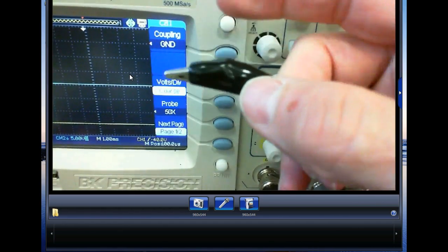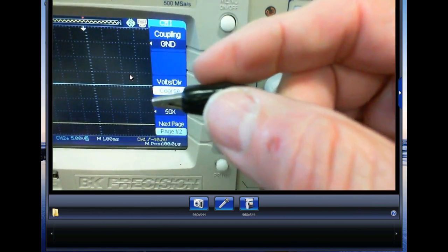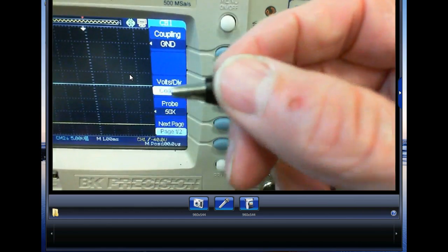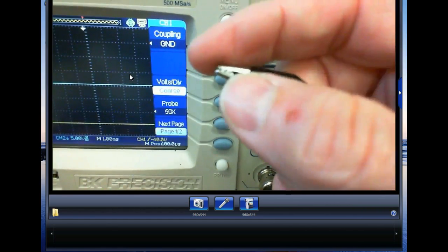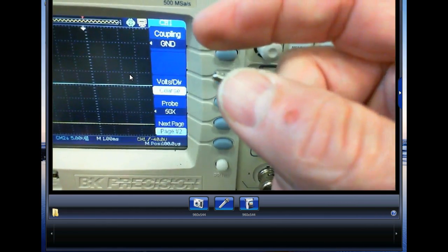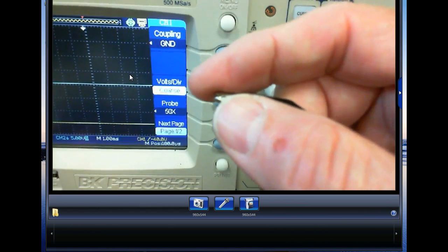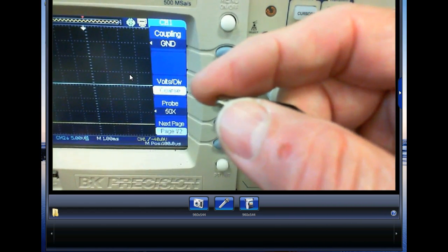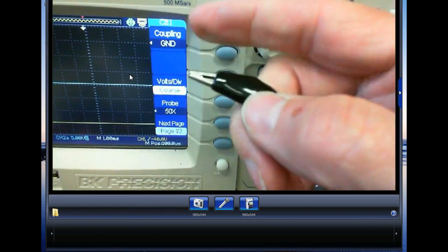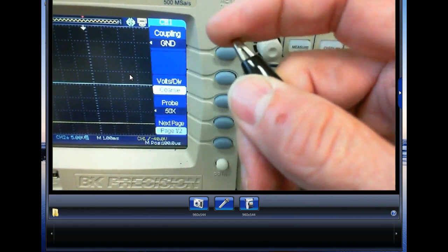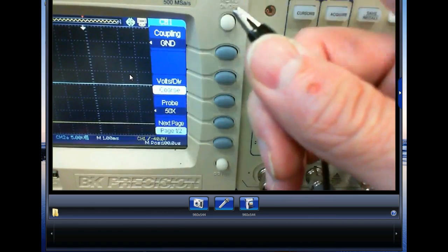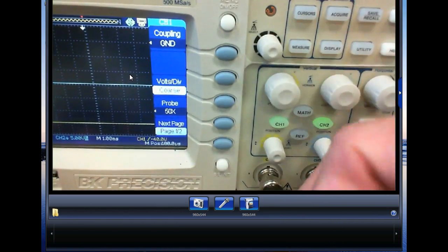So remember, now we're going through an isolated transformer, but as soon as you pop one of these things down, you've established common for the circuit, right? Or you've actually established a ground on the circuit, and you cannot probe through the circuit with this guy right here. You can with this guy right here.